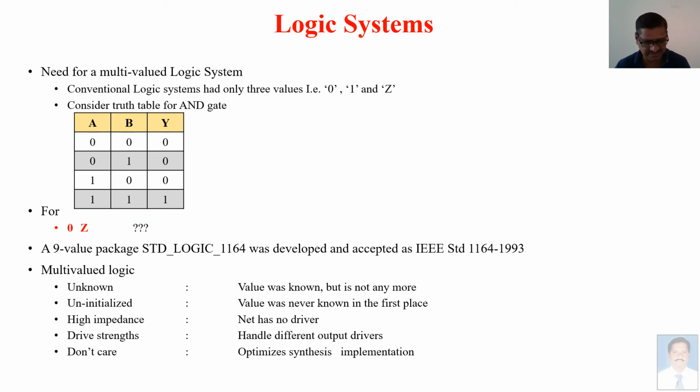In such cases, a 9-value package, std_logic_1164, was developed and accepted as an IEEE standard, 1164-1993. It is known as multi-valued logic. It has other logic levels or values.